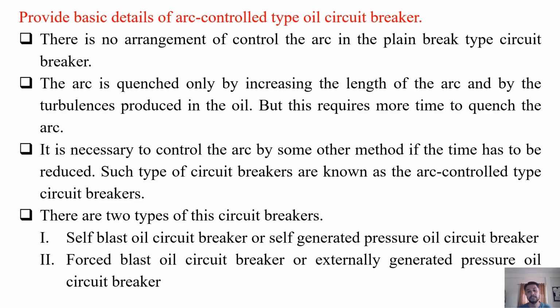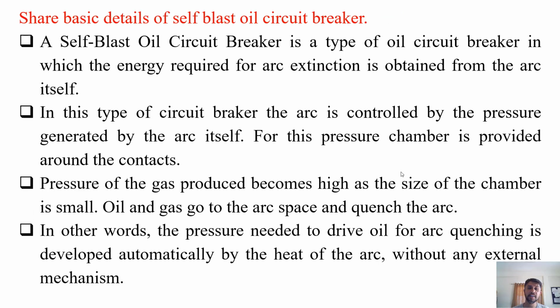There are two types of these breakers. One is self-blast oil circuit breaker or self-generated pressure oil circuit breaker, and second is forced blast oil circuit breaker or externally generated pressure oil circuit breaker. So this is the basic detail of arc control type oil circuit breaker.